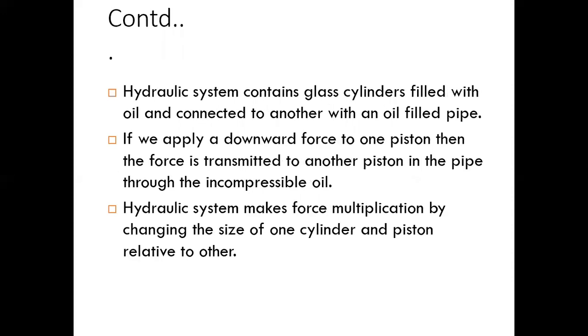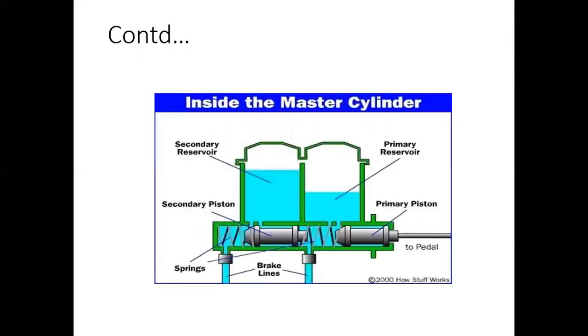The hydraulic system contains glass cylinders filled with oil and connected to one another with an oil filled pipe. If you apply a downward force to one piston, the force is transmitted to another piston in the pipe through the incompressible oil. So the hydraulic system makes force multiplication by changing the size of one cylinder and piston relative to the other.